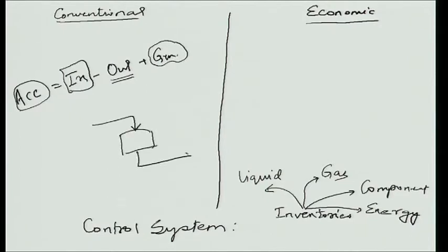In that very simple tank example, if I do not make sure that the inlet feed, let us say I am flow controlling the inlet feed, and let us say I am controlling the outlet, if the outlet does not exactly match what is being fed in, here there is no generation term. This level controller is basically ensuring that whatever is being fed in, exactly that same amount is being taken out, so that accumulation gets driven to 0, so that your process settles to a steady state.